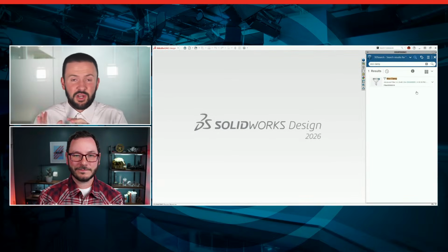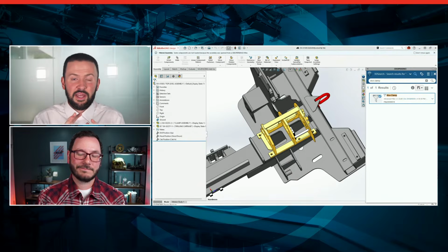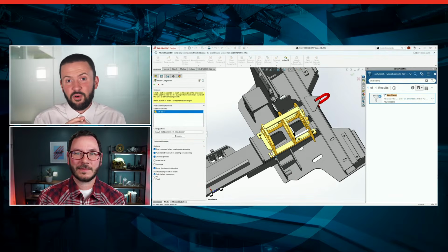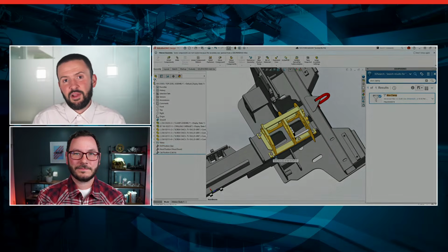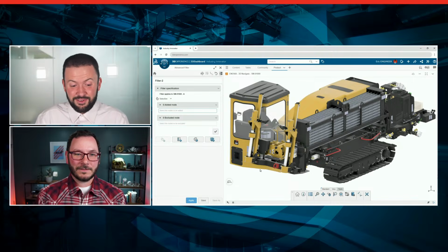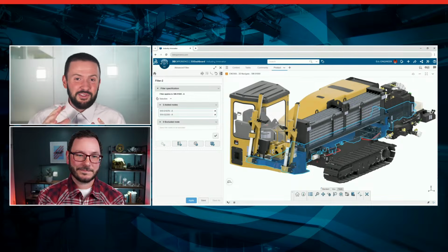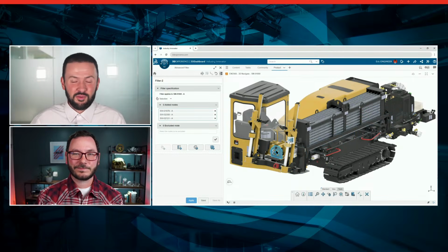So you're able to drag in the filtered version of the assembly and make changes there, and any changes you make inside of there will then be reflected through to the top level, because you're basically just working on it in a different capacity. So this one, I think, is going to be very interesting to continue to explore into FD01, FD02, FD03 as it continues to be enhanced, but also to explore throughout the rest of this episode, to be frank. We'll show different ways of filtering, different ways of taking advantage of those filtered assemblies inside of SOLIDWORKS.